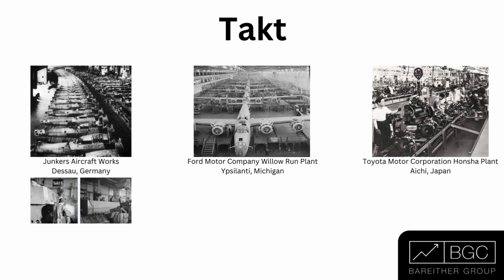So how do we calculate takt time today? Because takt is a time interval, it's measured in units of time, commonly in minutes or seconds for most production processes I've been around. To arrive at this production time target, we have to take the available working time in a day and divide it by the number of products required to meet demand in that interval.